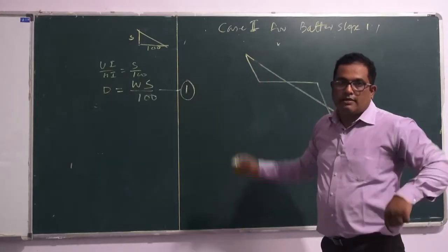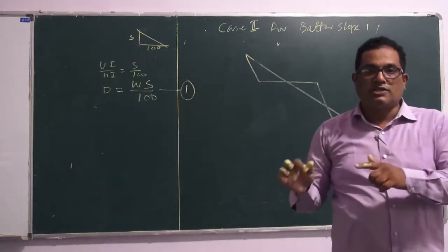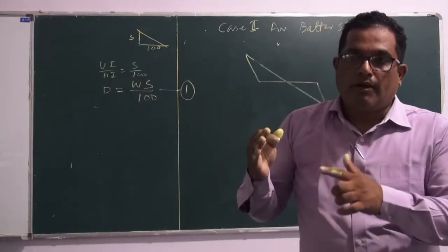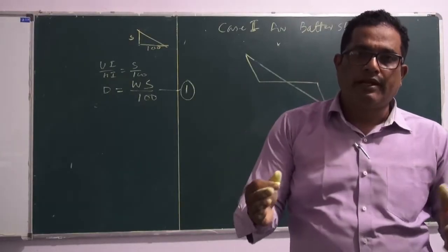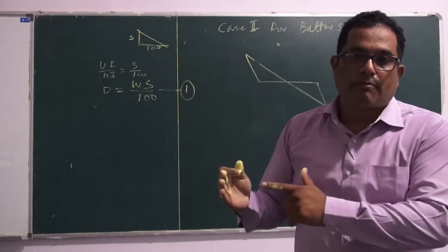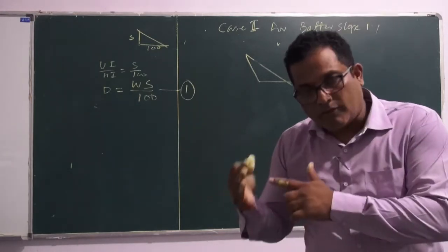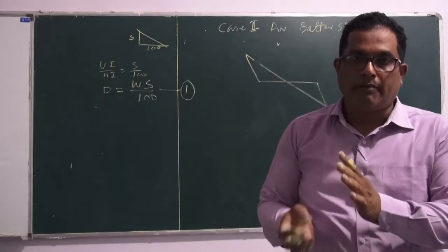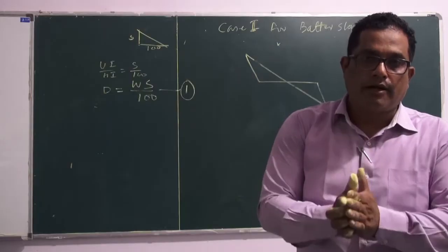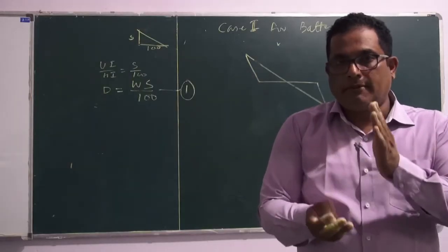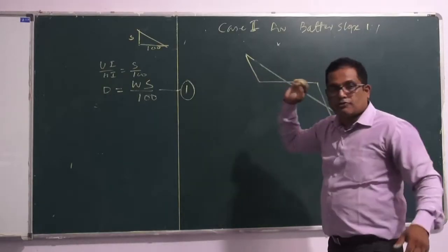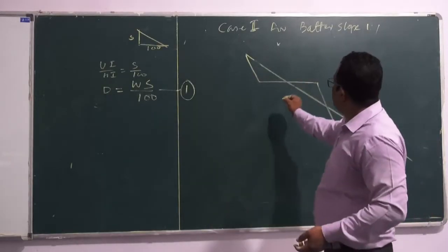So why do we do this? If the soil is not stable, or secondly, when we have to go for depth of cut beyond 1 meter, and also the soil type does not permit, and also where we don't have locally available rocks or any materials to retain the depth of the cut, then we have to go for riser slope, either 1:1 or 1/2:1.